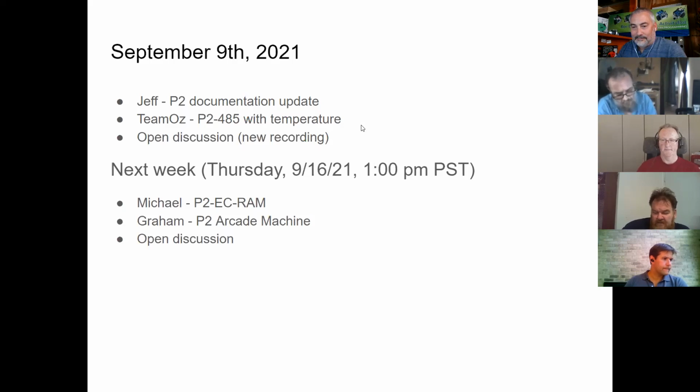It is possible to change the function of F12 in the Propeller tool; it just calls up an external executable, and so you can replace PST. In our case, we replace it with a chain of things. So you just call whatever program you need in the chain, and then that program can call PST, or it can call some other debug display, and so you can hook all that onto the existing infrastructure. For more advanced users, if they want to change how it operates, it's useful if you want to do some kind of data transfer before you get into the terminal.